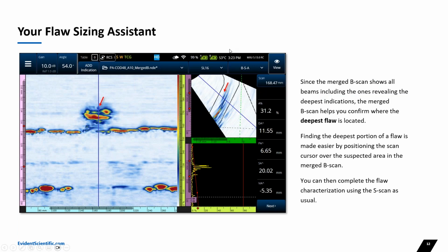In some cases, as promised regarding the flaw sizing, which I touched on briefly at the introduction slide, it's possible to have an estimation of where the deepest part of a flaw is located. My current interpretation is that it basically applies to the first leg, especially useful for ID flaws.